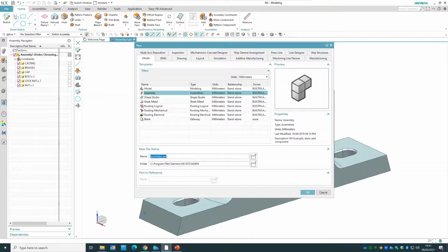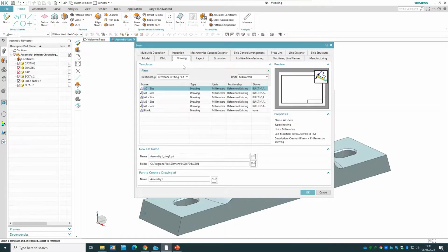Once you open it up, I'm going to go to the file and create a new file. And hopefully you remember there are different ways I could create a new file: from the menu on the top bar, from the file, or using Control N. Doesn't matter. So if you remember, we used to go to the modeling. But now for the drawing or 2D drafting, we're going to go to the drawing section. And now you can see there are different templates in there. I have to specify the units I want to continue and work with. Because I designed my parts using the millimeter unit, I have to continue with that. And I need to specify what kind of template size I'm gonna go with.